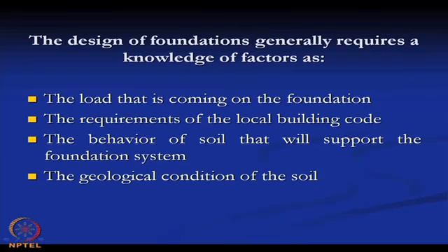Now, first, the design of foundations generally requires a knowledge of factors such as the load that is coming on the foundation, the requirements of the local building codes, the behavior of soil that will support the foundation system, and the geological condition of the soil. These things are very important when you design a foundation. We should know how much load is coming on the foundation.